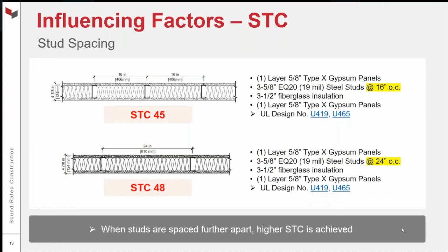Now, if we had a 2-hour wall with 4 layers of gypsum total, the difference might be not quite 3 points, but generally speaking, if your studs are spaced further apart, you're going to see slightly higher STC than you would with closer stud spacing.